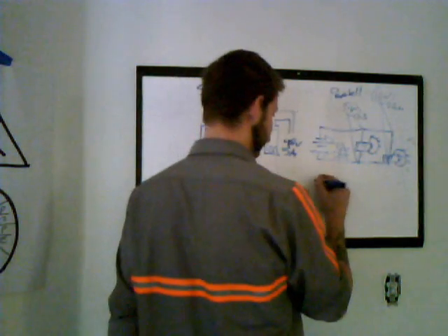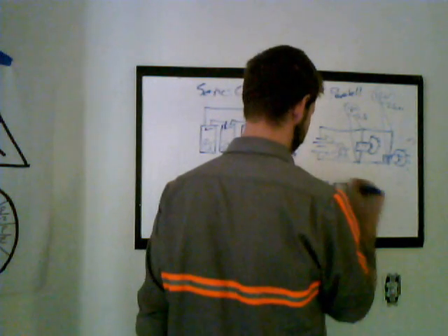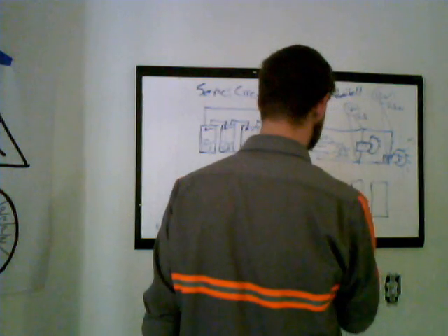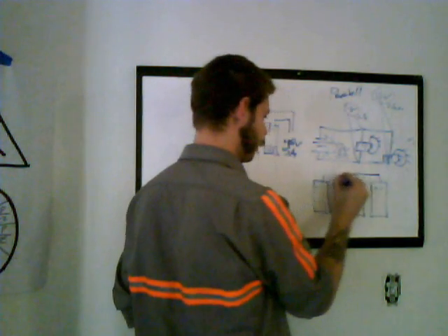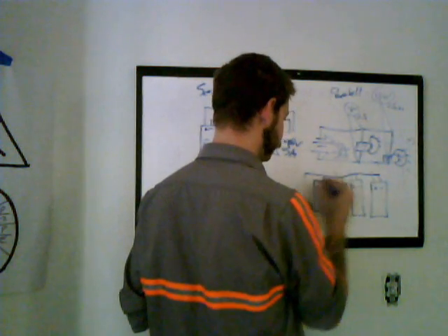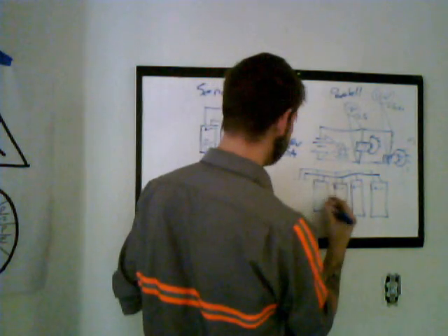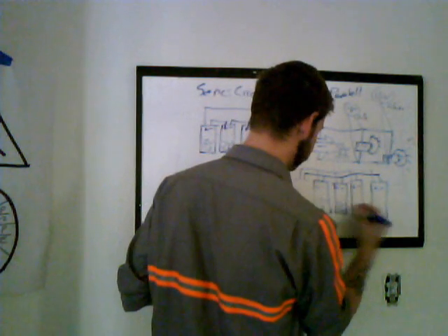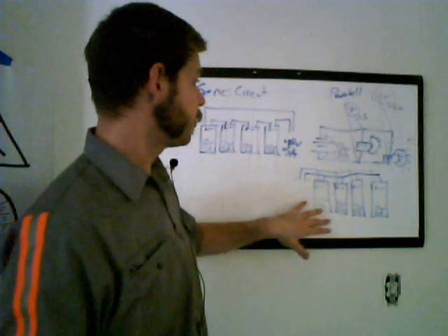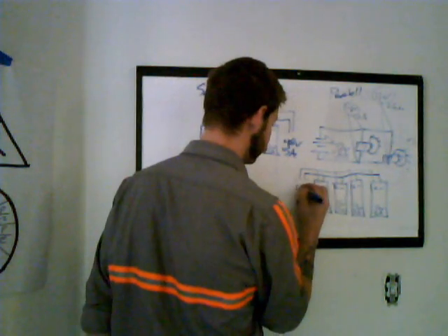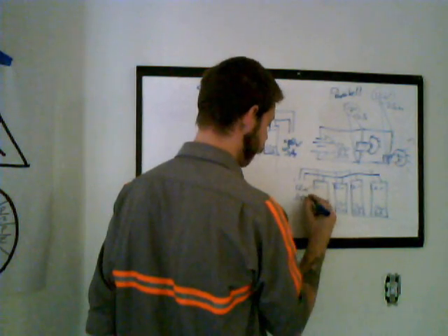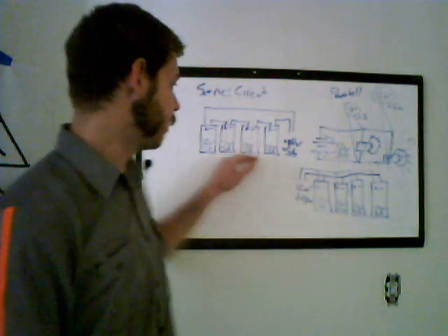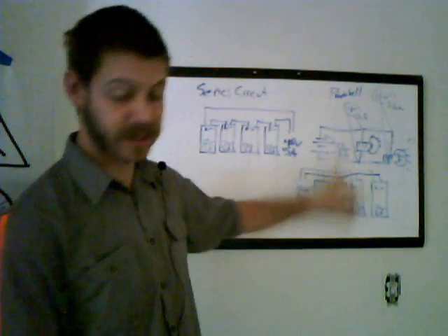All right. PV panels are exactly the same, but with gaining power. The way you put these together in parallel is you take all the negative ones out, and take all the positive ones out. These are all 12 volts, 5 amps too. Because these are put together in parallel, it's going to come out at 12 volts. But these amperages are going to stack on top of each other, just like these two amperages stacked on top of each other: 5, 10, 15, 20. It's going to be 20 amps. This cell came out at 48 volts, 5 amps. This cell came out at 12 volts, 20 amps because of the way it's wired together.